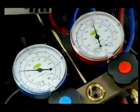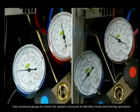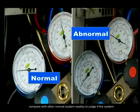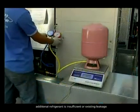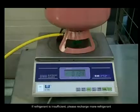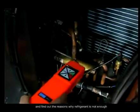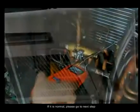Step 2. Use a pressure gauge to check the system pressure in standby mode and during operation. Compare with other normal systems nearby to judge if the system's additional refrigerant is insufficient or there is leakage. If refrigerant is insufficient, please recharge more refrigerant and find out why the refrigerant is not enough. If it is normal, please go to the next step.